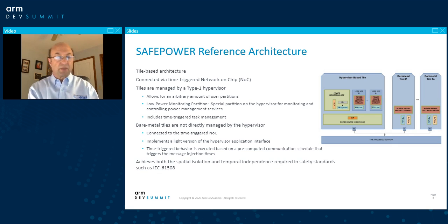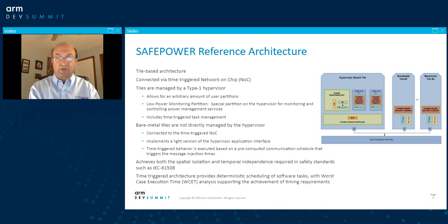This achieves both the spatial isolation and the temporal independence that's required in safety standards such as IEC 61508. This time-triggered architecture also provides deterministic scheduling of software tasks, with worst-case execution time analysis supporting the achievement of timing requirements for those safety-critical systems that have hard timing requirements.